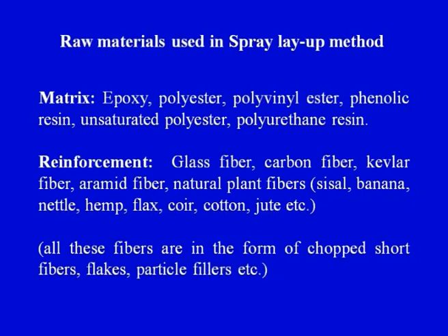The raw materials used in the spray layup method are again the same: epoxy, polyester, and polyurethane resin. The reinforcements can again be glass fiber, carbon fiber, Kevlar fiber, or natural fibers such as hemp, flax, coir, cotton, etc. All these fibers are in the form of chopped short fibers, flakes, particles, or fillers.